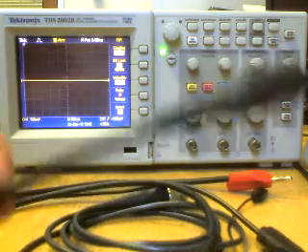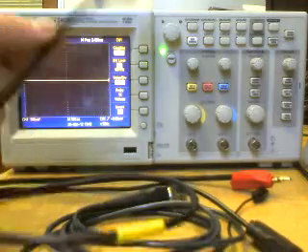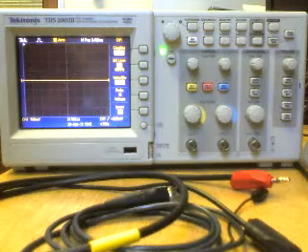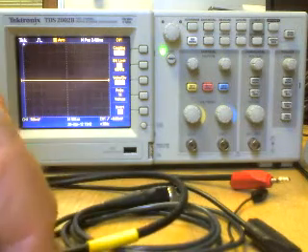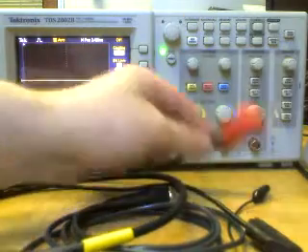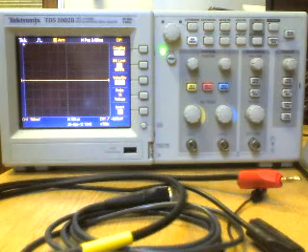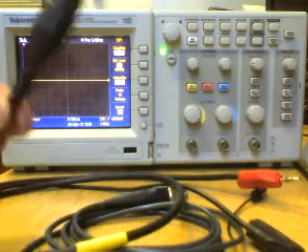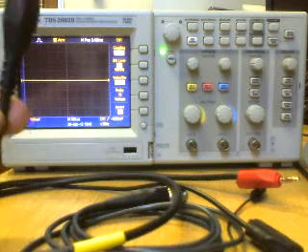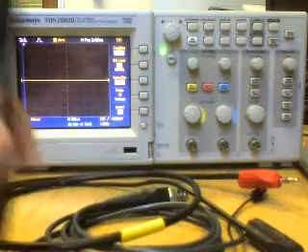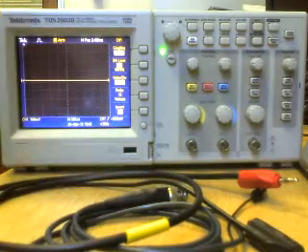Okay. Now, if this was set to ×10 and you used one of these BNC probes, what would you see on the screen? Well, you'd have 1 volt at this end, you'd have 1 volt at this end, but because this is set to ×10, it would actually multiply it by 10. So the value that you're reading would be 10 times bigger than what you were actually inputting into the oscilloscope. Okay, so you must pay attention to your probe settings.